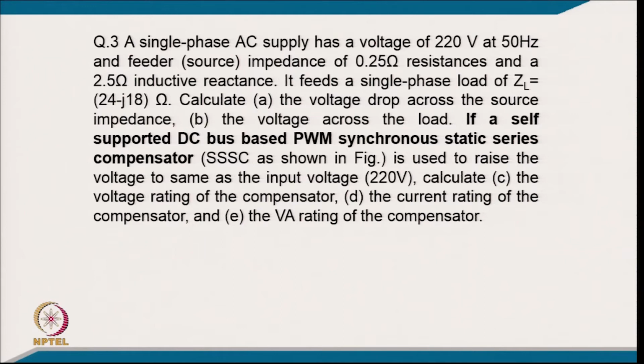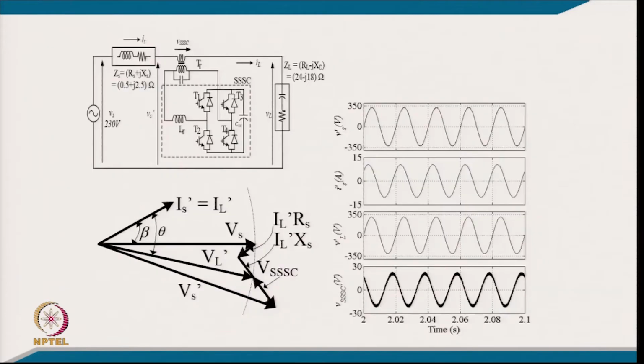If a series connected DC bus based synchronous static compensator is used to raise the voltage to the same as the input voltage of 220, calculate the voltage rating of the compensator, current rating of the compensator, and VA rating of the compensator.